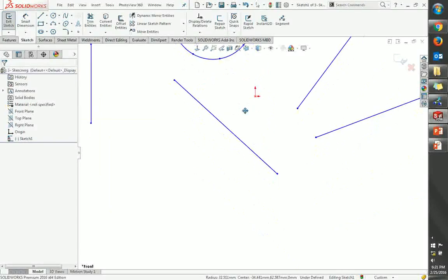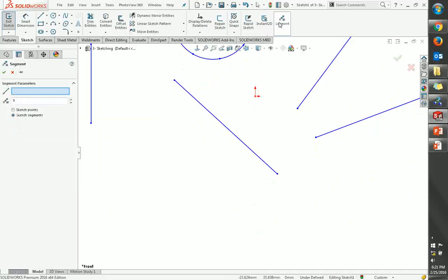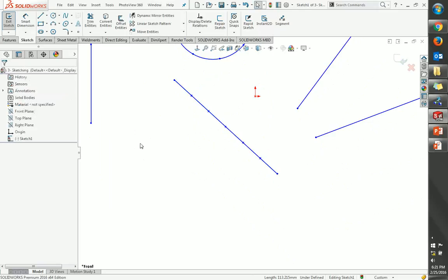The other way that you can use that is going to be this way. Under segment, I'm going to go ahead and pick the line. You can utilize sketch points in there. All right. So I'm going to go ahead and we'll knock this down to whatever number. We're going to say 5. I say OK to it, and then as soon as I say OK, I realize that I needed 4, not 5. I was counting the points, not the segments. Ah, dang it. So I'm a little messed up right now.